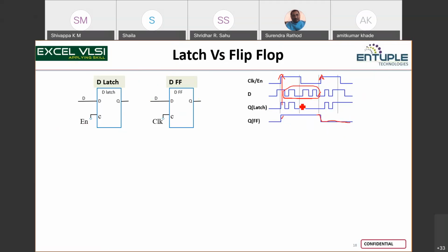So that is where, except for memories, we mostly prefer flip-flops, because of all these transients we call glitches, which could be unwanted changes, pulses of different widths and some noises. I want to filter out everything. Only the stable value I want to take and then pass on for reliable data transfer.